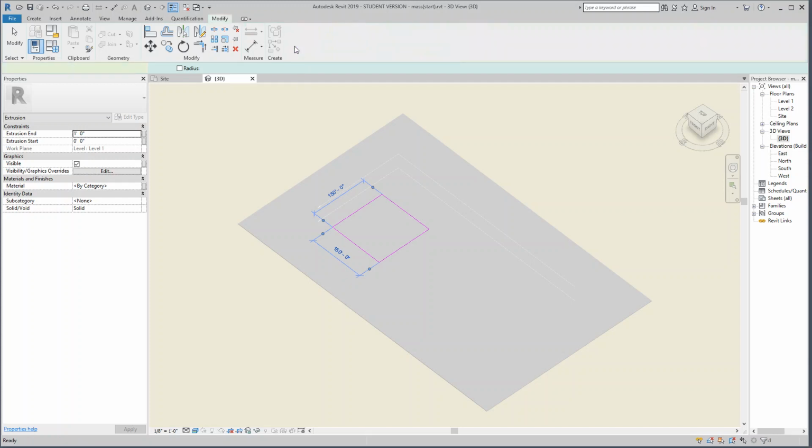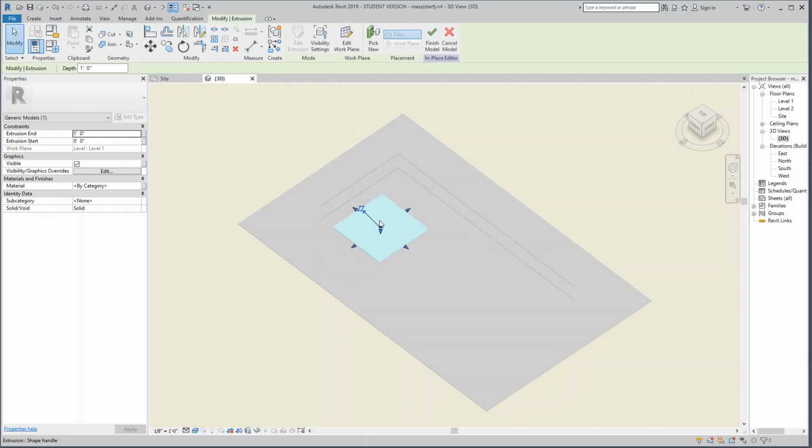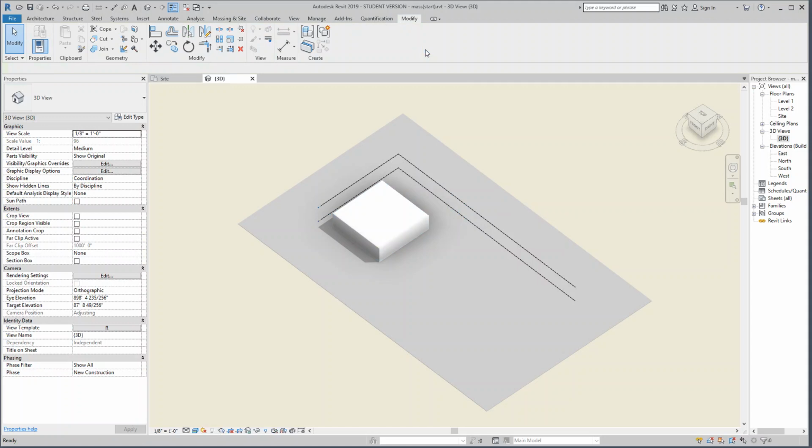And we'll click Done. Now we have a little flat surface. I'll go ahead and just pull that up. And you can see it's highlighting to level connected to level 1. And I could actually just lock it there and that'll behave parametrically. So let's finish that model off.